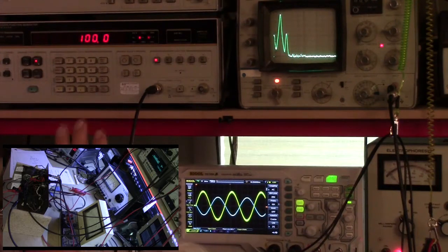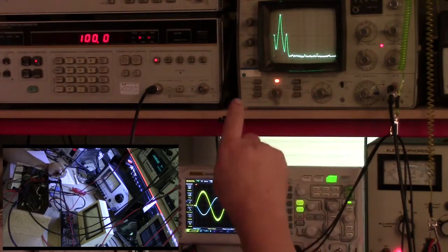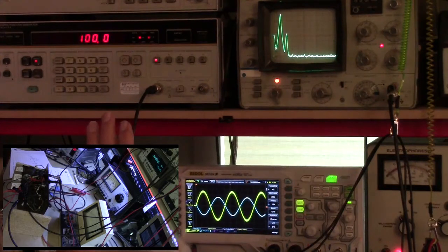And you could expect to get, from what I read, which we'll look at here in just a minute, 100 millivolts is pretty common for a humbucker. As the signal decays because the string stops vibrating, you should expect maybe 50 millivolts on average. Well, we can go look at that in just a minute, for various types of pickups, but this is at 1 kilohertz at 100 millivolts.